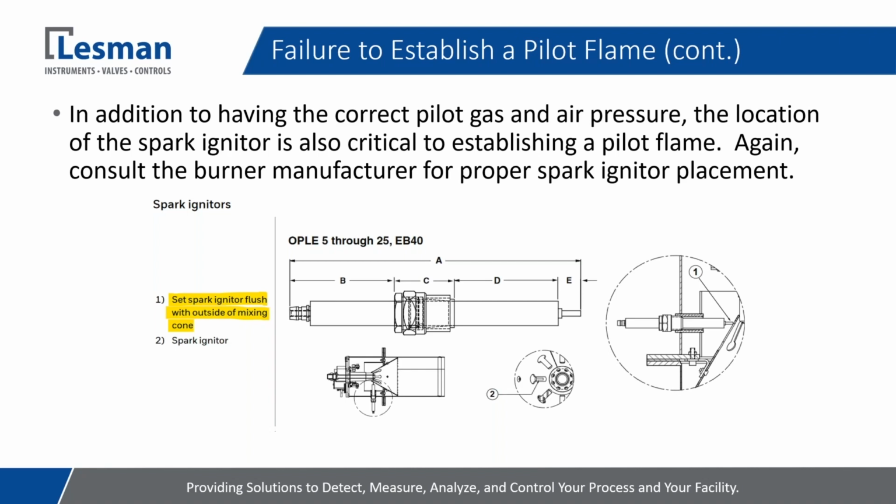So if you look at the area immediately after the pilot inlet, if there's not a lot of airflow at that point, it may be a little too rich to ignite at that point. And then if you go too far outside of that zone where you've got more dilution air coming in, the igniter might be a little too lean at that point.